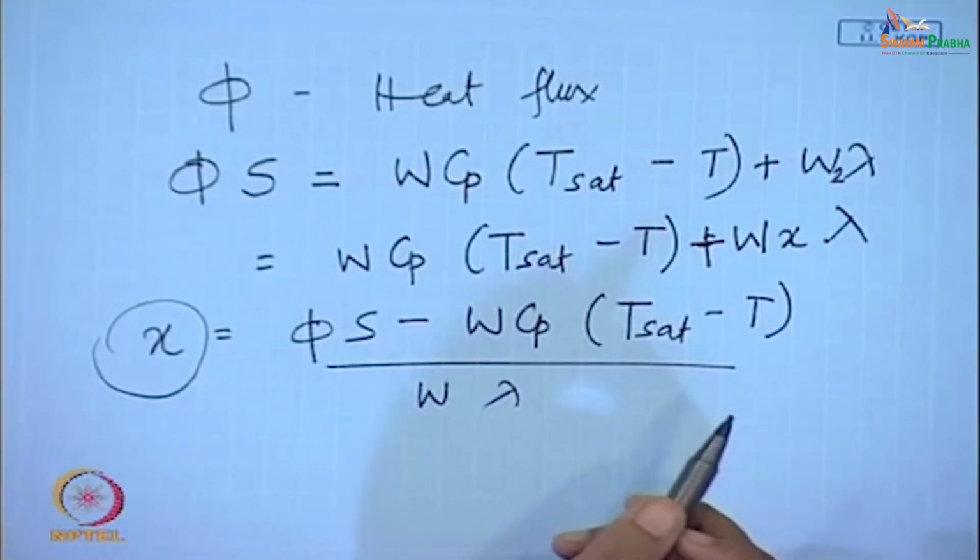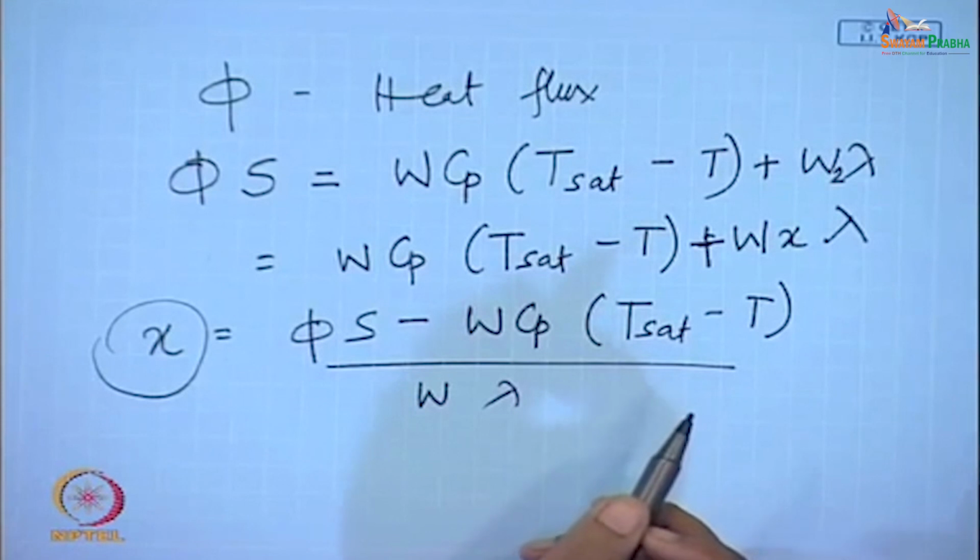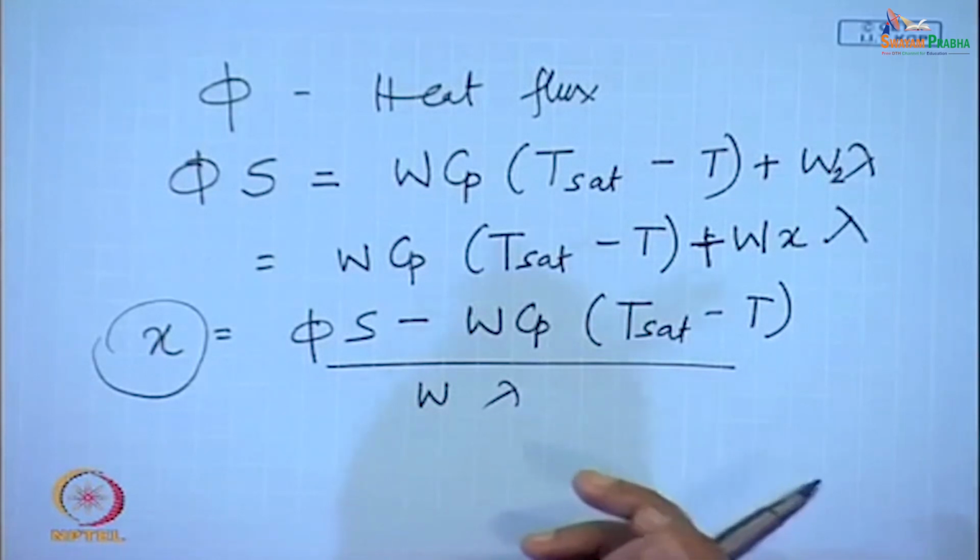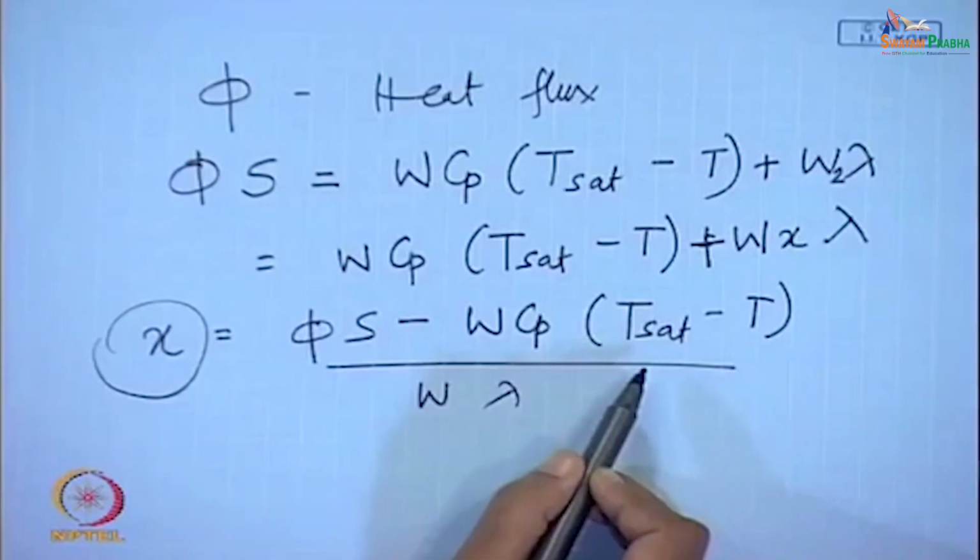Now, if we have liquid and vapor, any questions, any doubts, you are free to ask me. Okay. So, this is the expression when we find that liquid at below saturation temperature is flowing. Now, suppose we have a liquid vapor mixture in equilibrium with one another. Under that circumstance, say if it is steam water flow, we can directly refer to the enthalpy values from the steam tables, and we can find out x, is it not?